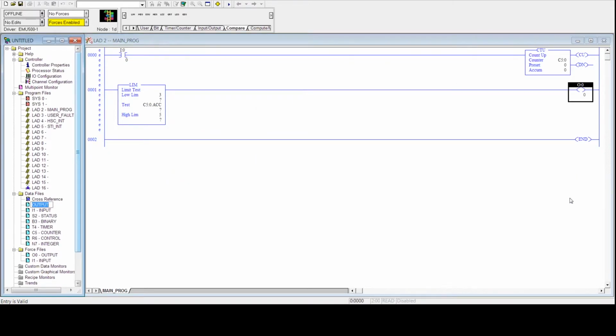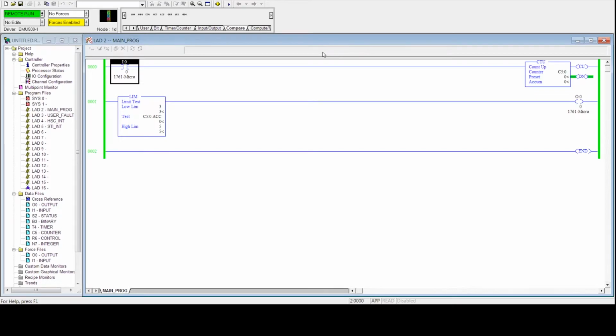So let's fire this up and test it out. Alright, I have put it online, and you will notice this is all going. Let's count it up to 3 and see what happens. As you see right now, it is below 3, so nothing is on, just as we expect. Let's toggle this bit. Okay, we're at 2. We're at accumulated value of 2 and 3. We have equal 3 now. If 3 equals 3, this is on.